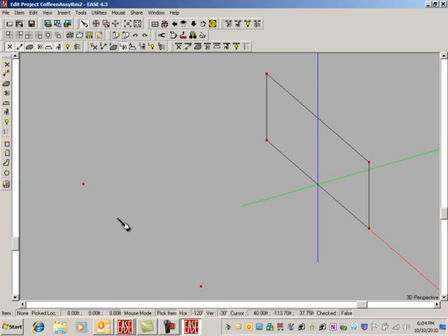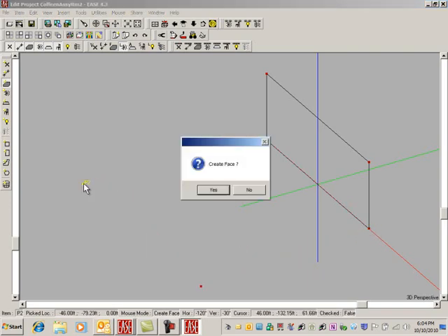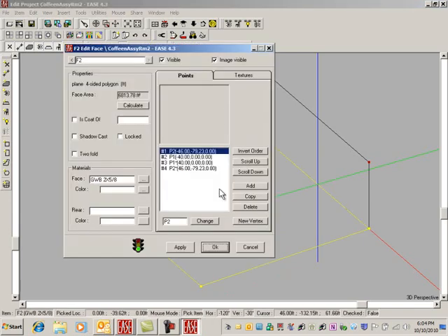We could do that by simply putting a vertex up here. We could take this vertex right here, and we know it's up 30 feet to the ceiling, so we could duplicate it, not get rid of the Y stuff, and in the Z direction, we'll take it up 30 feet. Just like this. Okay. There we are. Now we have our roof, and we could make it anytime we liked. We could just do that right now.